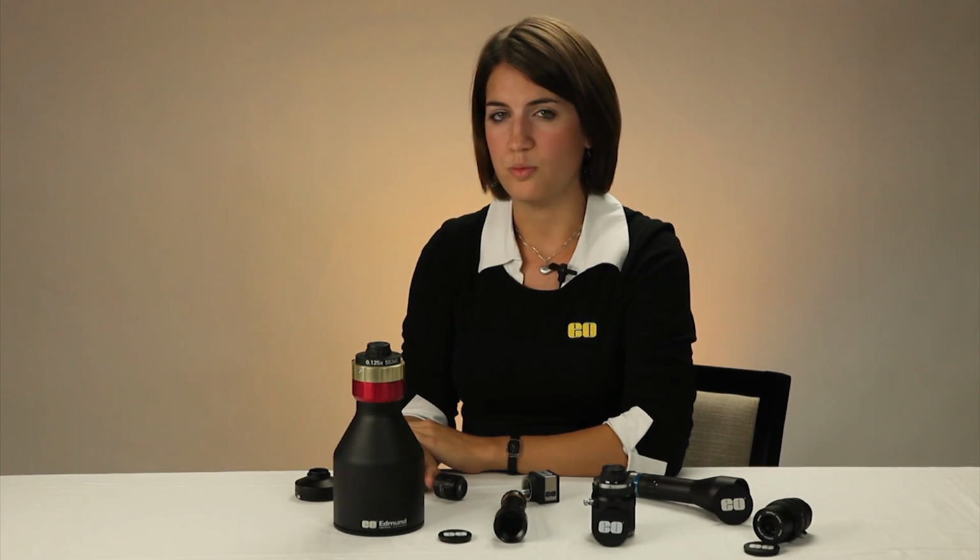T-mount refers to an M42 by 0.75mm thread. Although the original T-mount standard refers to a 55mm flange focal distance, the T-thread is used with a number of different flange distances, most commonly the 6.56mm and 19.53mm, which are somewhat popular with the large sensor formats. This is not to be confused with the less common M42 by 1mm thread, which does not have a standard flange distance.